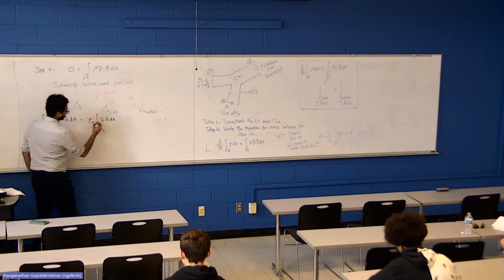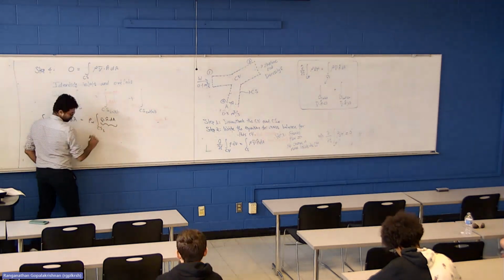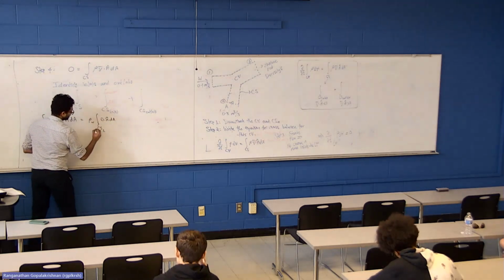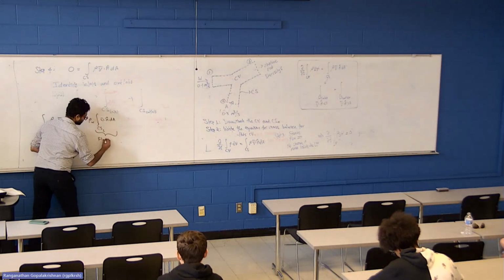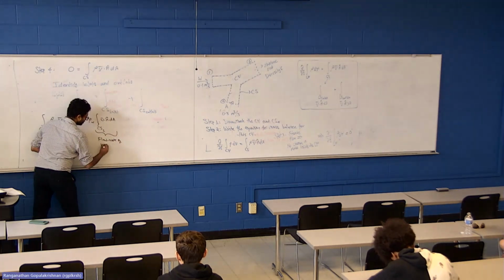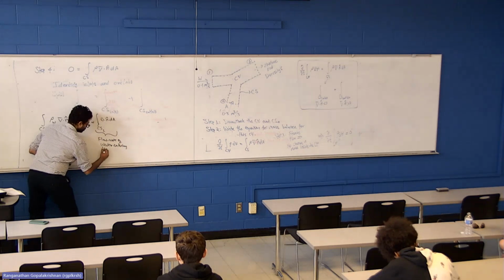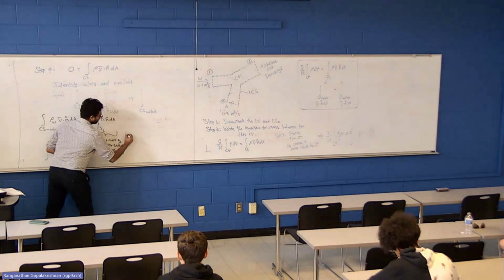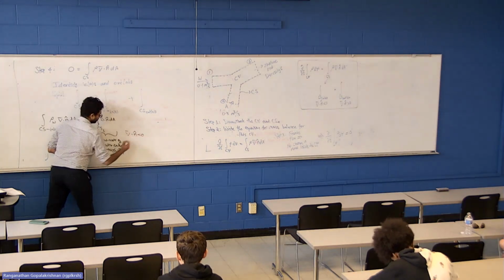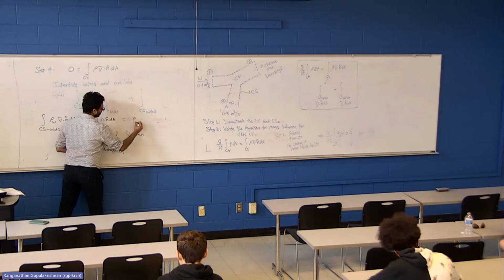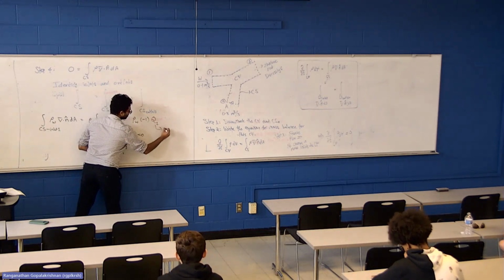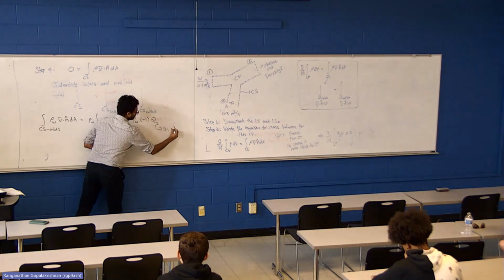Now we know that this expression is the flow rate of water entering through section 1, but we adopted the convention that V dot n is negative, so this would be rho w times minus q1, where q1 is 0.1 meter cube per second.